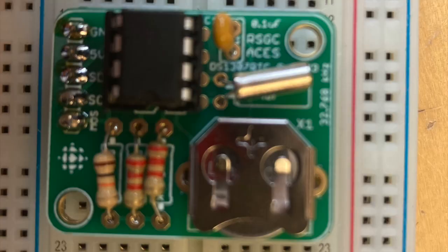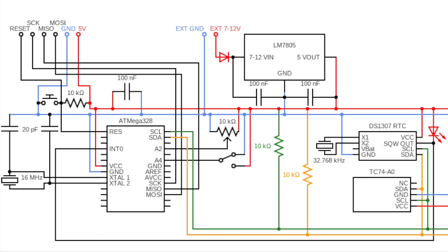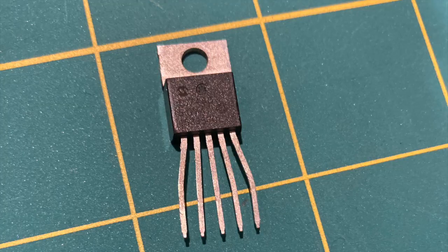The next piece added is the real-time clock, which contains the data for the active hours, minutes, seconds, day, date, month, and year. As long as it's connected to power, it's able to consistently update the data within its storage accordingly. The data is received from the computer from a special example code in the time library. It's also able to provide a constant square wave output, which is used for an interrupt function within the program. The next added piece is the I2C compatible TC74 temperature sensor. This piece is pretty self-explanatory.